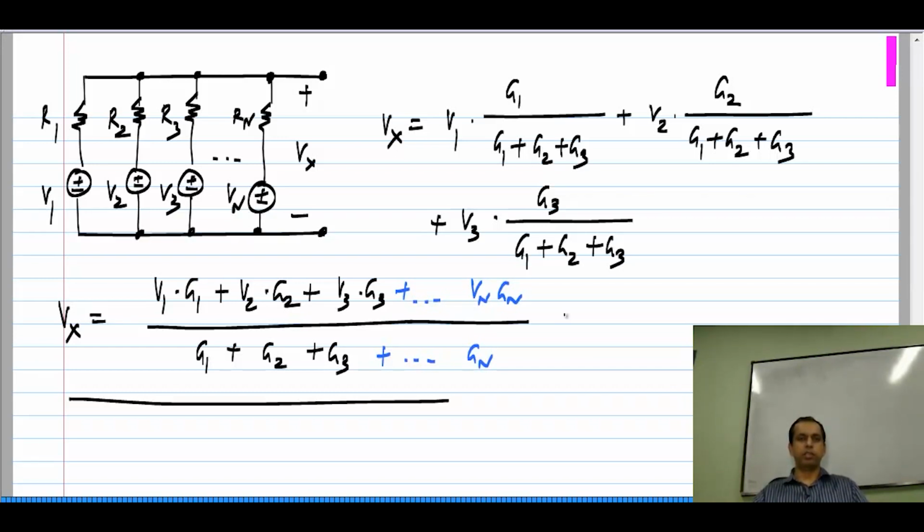Now, like I said, you can derive this in many ways. In particular, I would encourage you to try and derive this by using Thevenin and Norton equivalents suitably, but this is one way in which you could use reciprocity, right. My original circuit had multiple sources, and I wanted to calculate this particular output. Instead of that, I can turn this around and use reciprocity. I connect a single source here, and after that it was very easy in this case, especially because it was just a current divider. I had to find all these branch currents, and each one has some ratio to the original current, and I multiply all these voltages by corresponding ratios to get the final voltage. So, that is how you can use reciprocity in this case and also in many other cases.